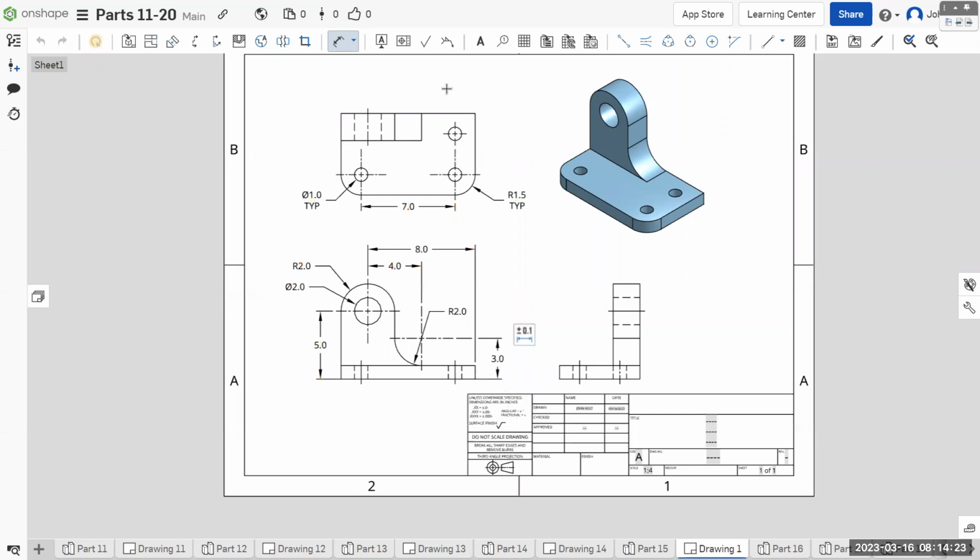And then for these, we need our distances, which are depth, but you know, up and down on the sheet for this view. So how are we going to locate this? Well, if we did it to the front, we'd have to cross over something. So we can do it from the back, and because these line up, we can do it like that.